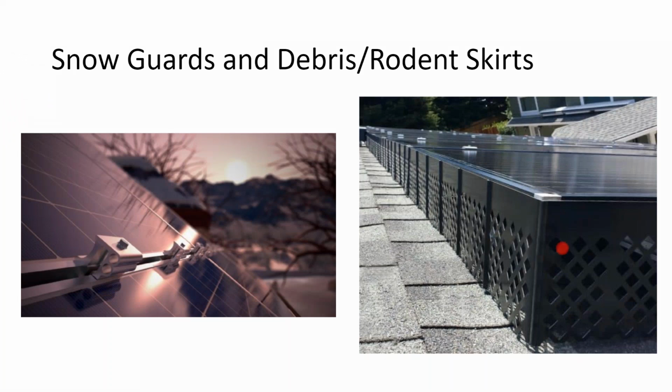Some other module accessories. If you have trees near your roof, you will want to put a squirrel guard around the array. Otherwise these become nesting areas, for squirrels or pigeons, and inevitably that leads to rodent damage. Here we have little clips that are designed for areas of heavy snow, where the concern is not the weight of the snow on the roof or the fact that there's snow on the roof, it's how the snow gets off of the roof. To prevent avalanches, they put a little bit of friction into the rack so that the snow sheds more evenly.